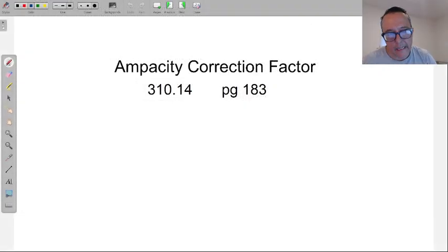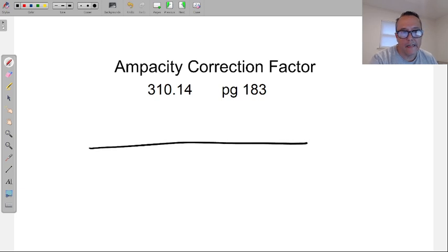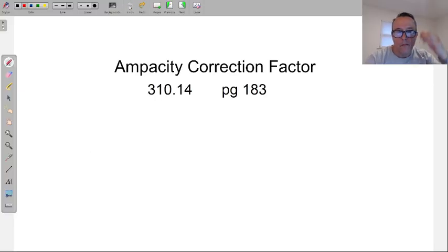Load current carrying conductors. All right, not just current flow, the way a lot of times you'll read that when you turn power on, current is flowing through the circuit. Yes, but it's not until you turn on the load that you get load current. That's the big amperage that we measure with our amp meters. This is the amperage that we set breakers to protect the wires from.